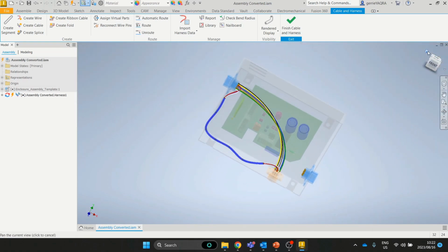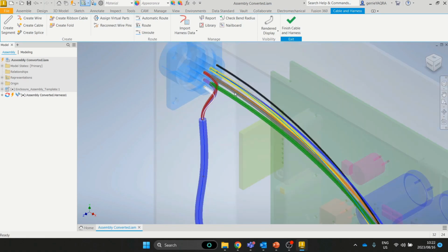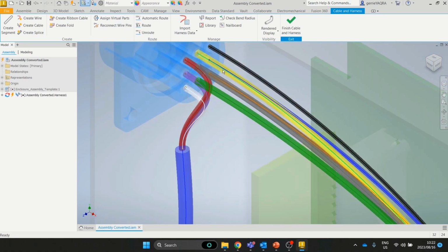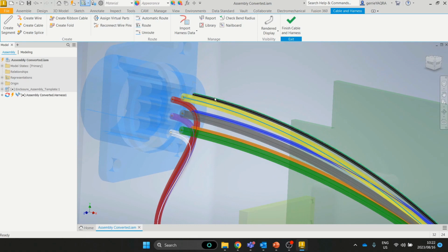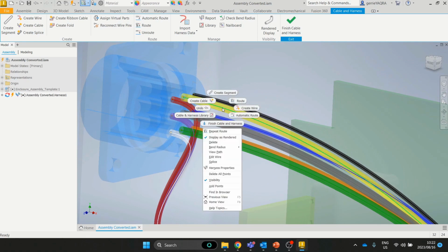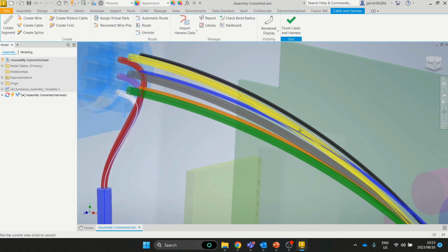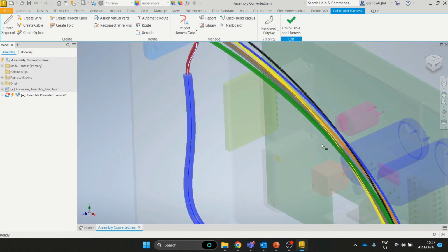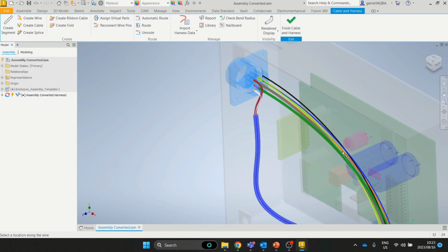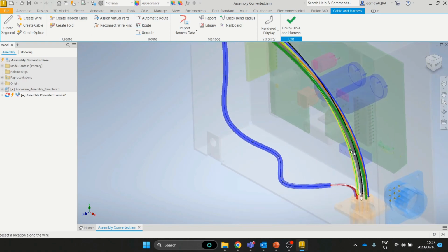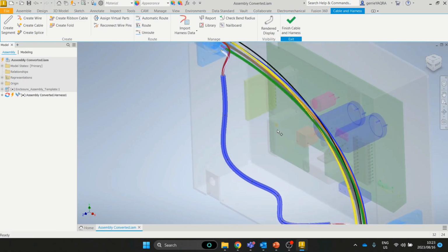So just an example for that, we can go and right click on a wire, and from here in our list we can find add points, and as we go through the line or the wire, center line with a dot, and that would be where your move will take place.